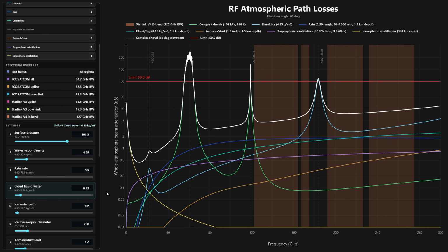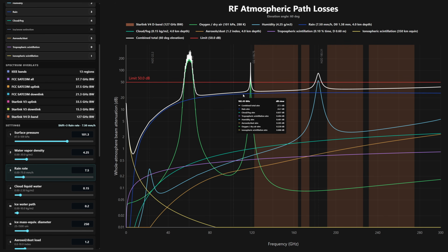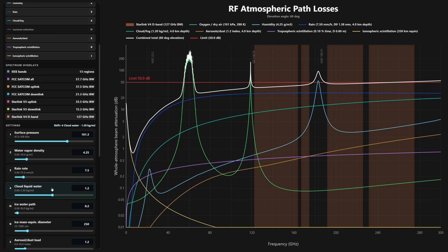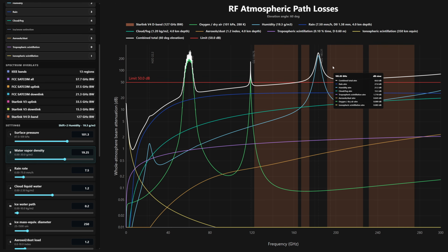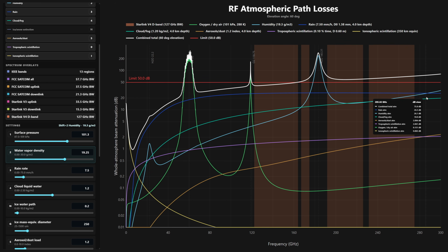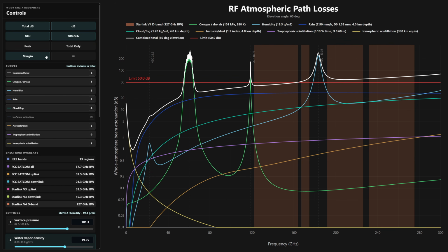In this frequency range, the rain attenuation remains high, but levels off as the millimeter waves become smaller than rain particles and closer to the size of cloud and fog particles. And this gradually causes more Rayleigh scattering and liquid water absorption. The gaseous molecular absorption of water gradually rises as well and spikes at 183 gigahertz and 325 gigahertz. So this makes the losses from humidity considerably higher. The overall losses are very high, but they can be overcome with much higher gain antennas in clear weather.